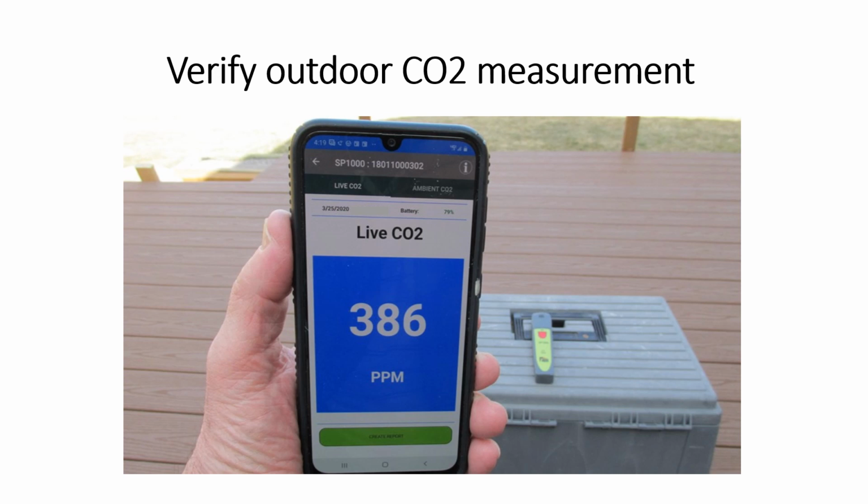For this non-dispersive infrared sensor, this will work for the accuracy of what you're going to encounter inside buildings to monitor air quality. And this is your starting point: how much is outside? And then we moved inside and began our test.